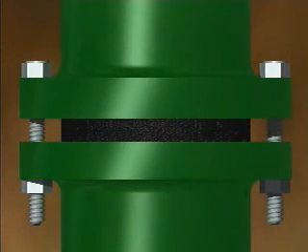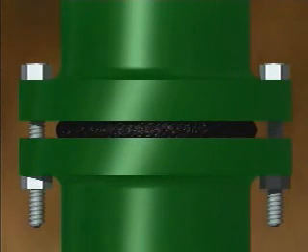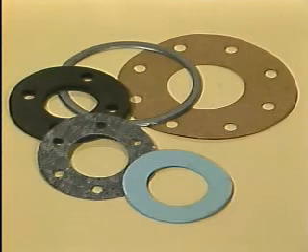The gasket is installed between the smooth sealing surfaces or faces on the connecting flanges at the end of each pipe section. As the flanges are bolted together, the gasket is compressed or squeezed between the faces. As the bolts are tightened, the gasket material is forced into any small imperfections in the sealing surfaces of each flange. As a result, leakage paths are blocked off.